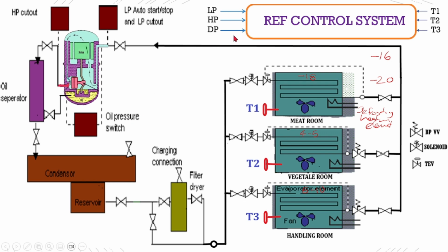And there is another safety device signal, that is the oil pressure switch. Of course, this is a reciprocating compressor, so you have to have oil to lubricate the rotating and reciprocating moving components. Internally there is a built-in pump, so there should be some way to monitor that pump pressure. So this is the device, the oil pressure switch.